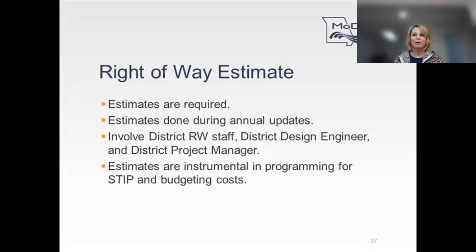Requests for a right-of-way estimate should be submitted to the district right-of-way manager by memo and as outlined in EPG sections 121.7 and 236.3.3.2. If plans are unavailable, a detailed description and aerial map can be submitted with the memo for right-of-way staff to utilize in preparing the estimates.